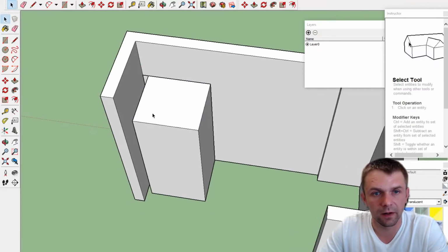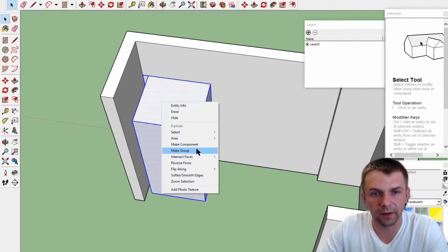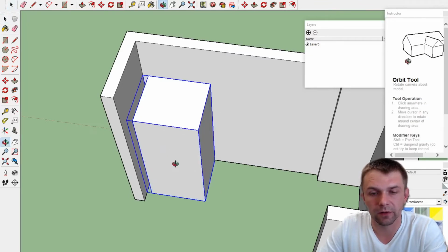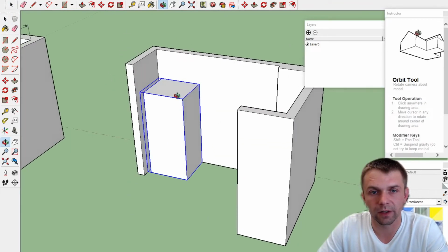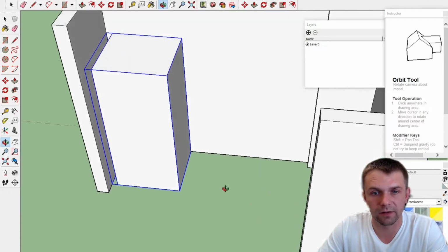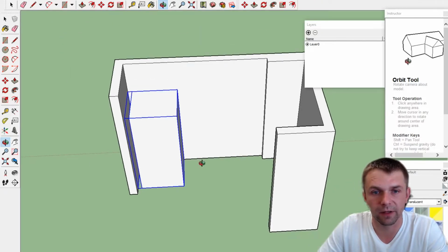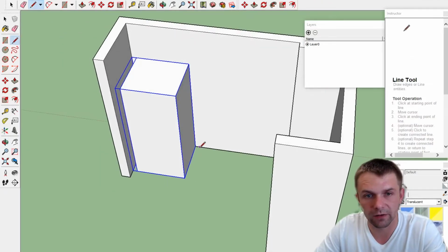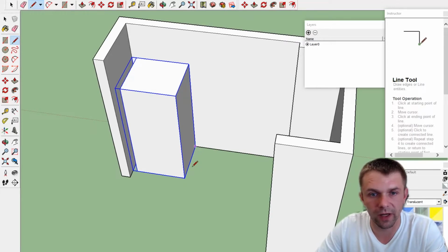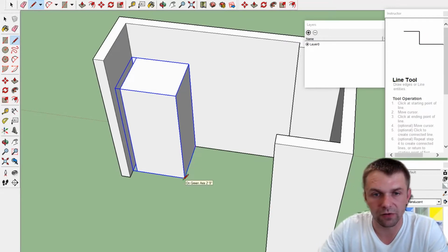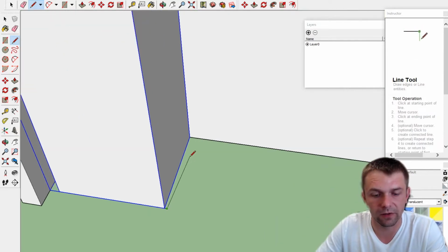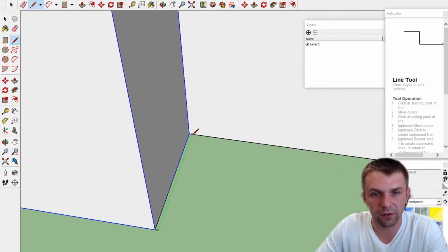Escape, and triple click, right click, make a group. So again, very important, work in blocks. In blocks, that's the number one trick in SketchUp. It's easier to edit. So L, then we do a finished gable, 30 inches deep, 0.75 or 3/4. And then one option is we can go back and close it like this.